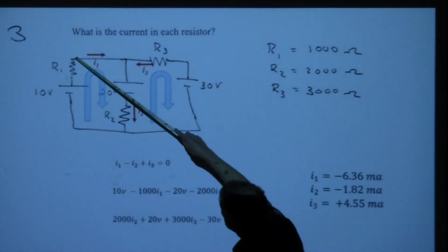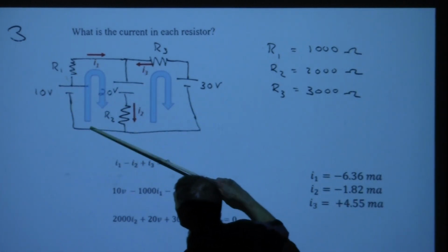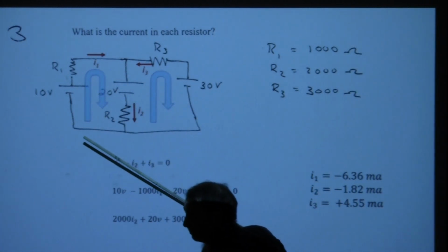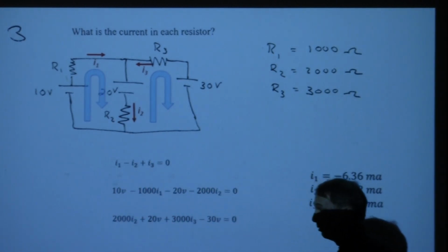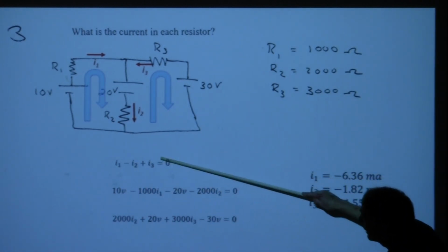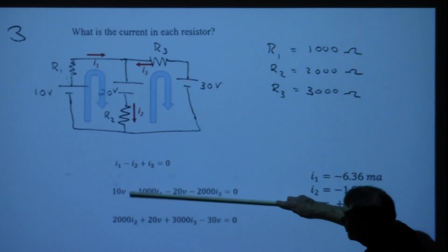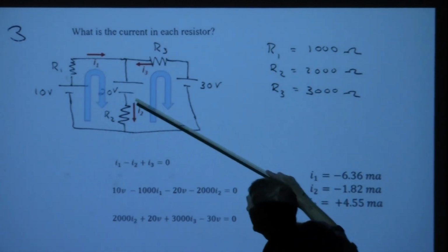You can also choose to do this outer loop. But be careful. Don't do 1 loop and 2 loops and then a 3rd loop, because that 3rd loop is a linear sum of the other 2, and you have redundant equations. So I do need at least one current and 2 voltage loops. In terms of how many loops you need, look at this like a window pane.